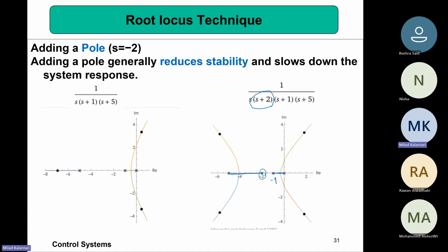And how about the centroid value? How to calculate the centroid value? Because I'm going to, let's say, find the asymptotes. For the centroid value, we need to add all of the poles. We want to know, when you are looking at a very far region, when these roots are basically concentrated, what you are seeing is the average of the poles and zeros.